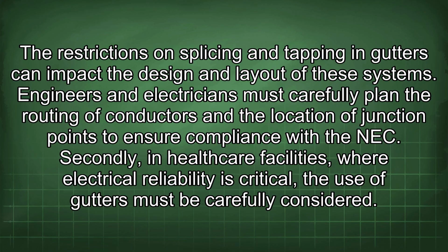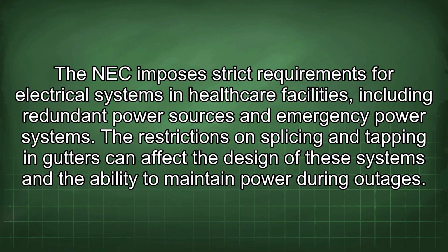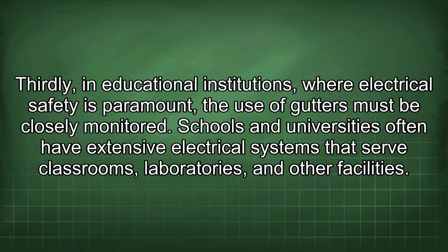Engineers and electricians must carefully plan the routing of conductors and the location of junction points to ensure compliance with the NEC. Secondly, in healthcare facilities, where electrical reliability is critical, the use of gutters must be carefully considered. The NEC imposes strict requirements for electrical systems in healthcare facilities, including redundant power sources and emergency power systems. The restrictions on splicing and tapping in gutters can affect the design of these systems and the ability to maintain power during outages.